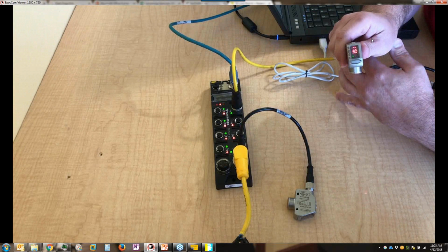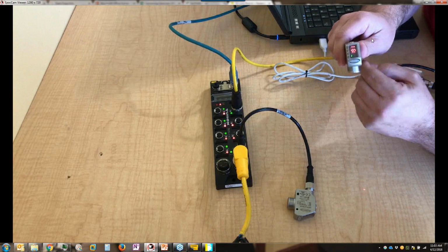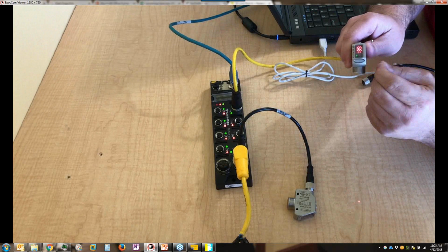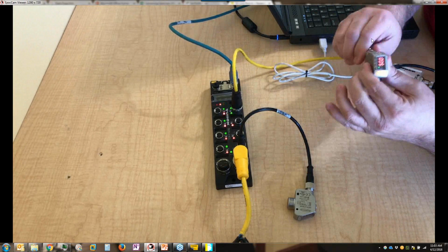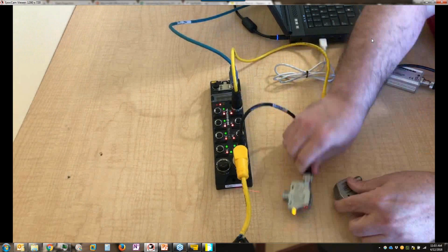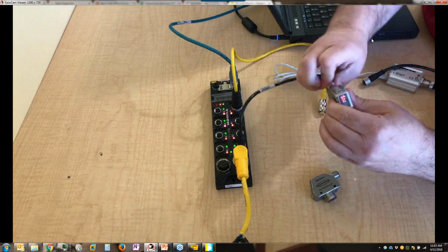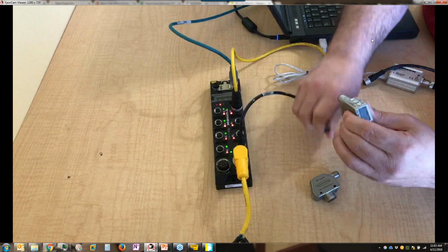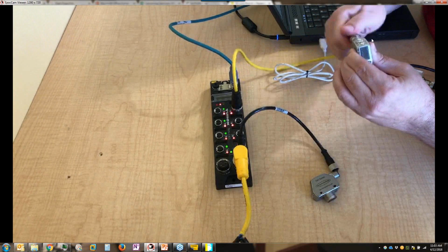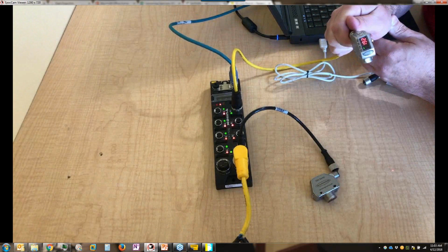So the master backed up or saved that new value, and once it did that, it flipped that bit, that DS flag or DS upload bit, back to the correct state. So now if I remove this at 175, take the other sensor that's normally reading at 150 and put it on to channel 4, we should also see that this sensor is going to be sent the new parameters via a restore, and it should read 175 as a trigger point.